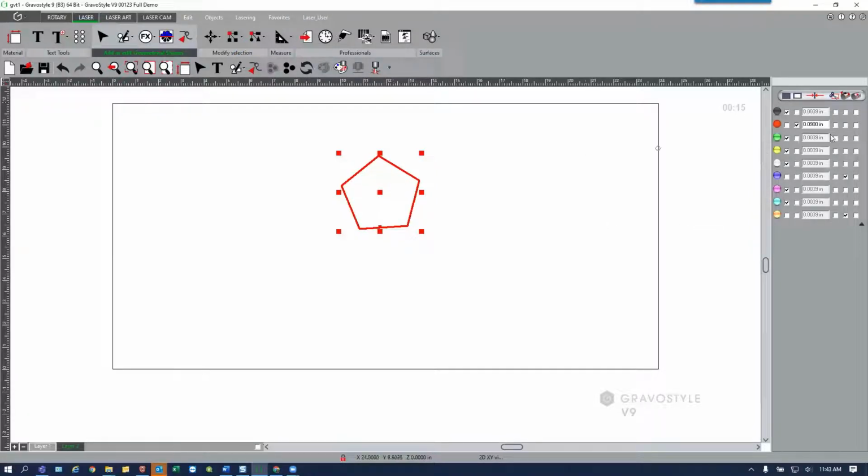A line that is less than 7 thousandths must be vector engraved. It would be considered to be a hairline. So the laser can't raster engrave on very thin lines. They need to be widened using this tool to add a contour and define the contour width.